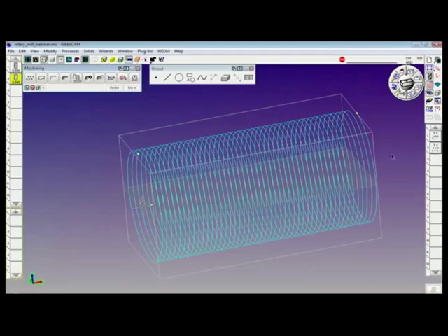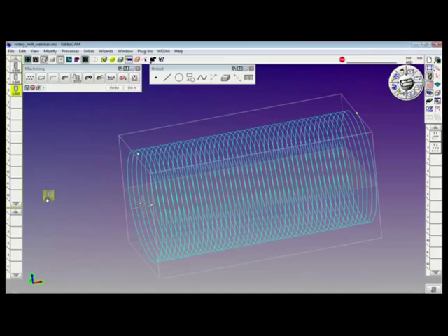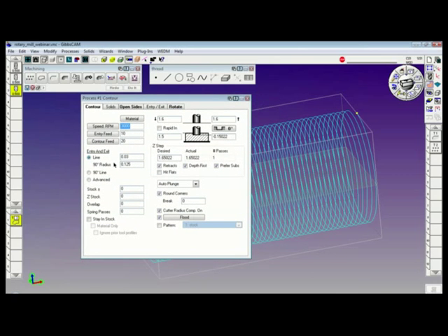Now, let's go ahead and machine this. Tool list, cam list, new tool. I'm going to machine it with a spot drill that's on a 60-degree angle to give me a 60-degree V. Everything else remains the same. Close the dialog. I'll bring this down, and as I mentioned, this is going to be a contour cut. Feed and speeds look good to me. Entry exit moves. I really don't need a radius, but I do need an entry line for compensation. Stock values are 0, overlap, spring passes are 0.